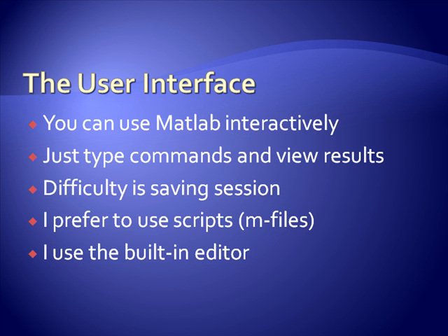These are just script files, and they're called M files because they have a .m file extension. They're just a list of MATLAB commands, and you save these in this text file. Then you tell MATLAB to run that script, and it'll run through the script and execute all the commands one by one, and you'll see the output. And there's a built-in editor just for editing those scripts, and we'll spend a lot of time in that.